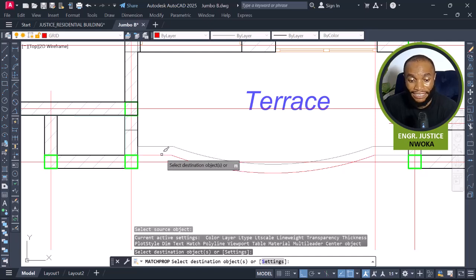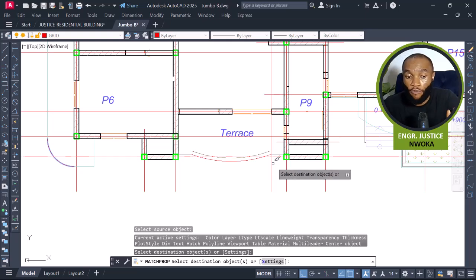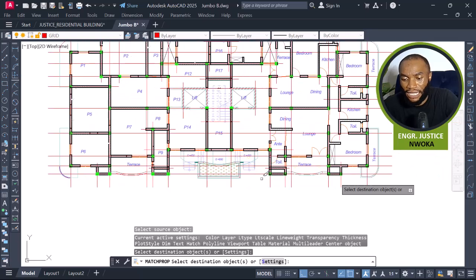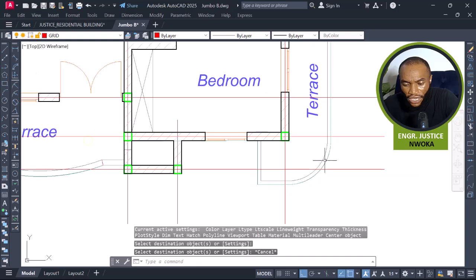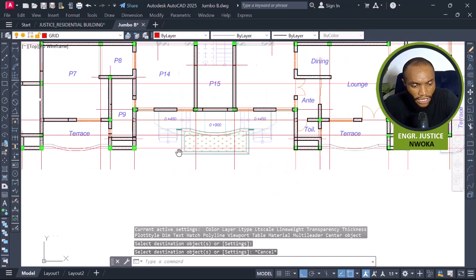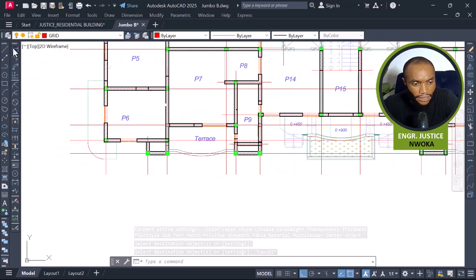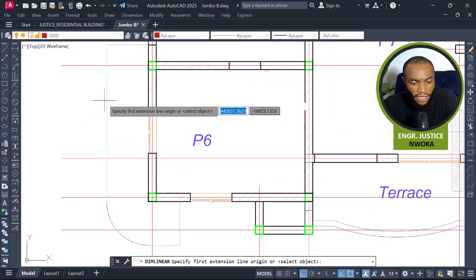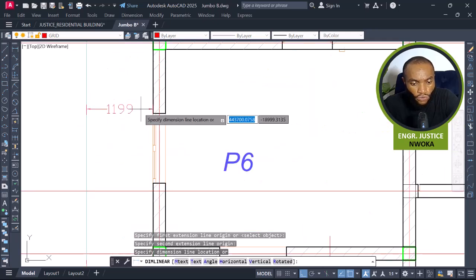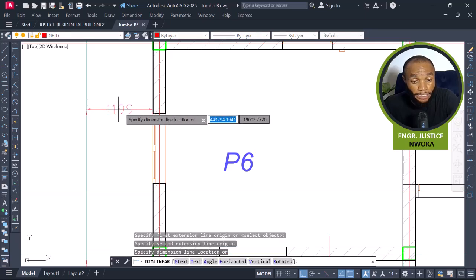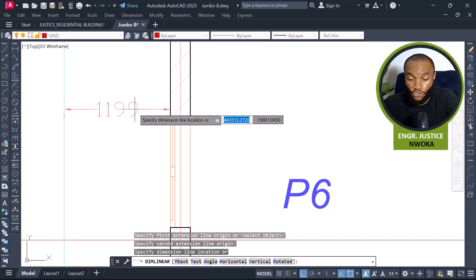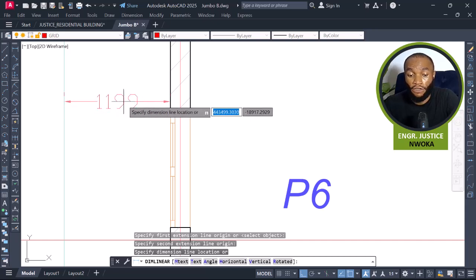We can get all the straight lines on the software perfectly, but all the curves must be converted to grid lines. Okay, that's fine. So with this now, I'll just convert all the curves here. And there are so many curves here. This is the one, and knowing that our distance of balcony cantilever here is what? 1.2. So from here to here is basically 1.2. Yeah, 1.2 approximately from the face of the wall here.